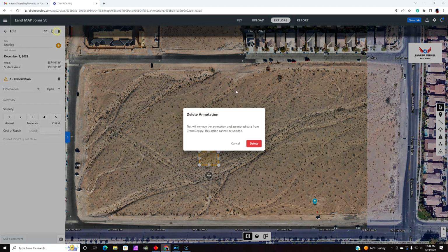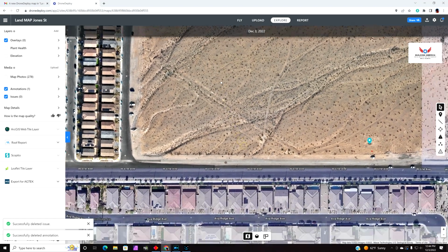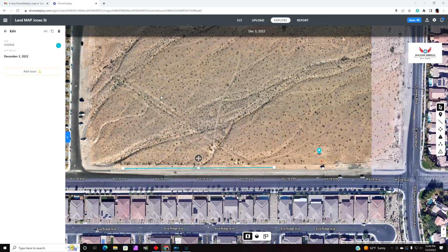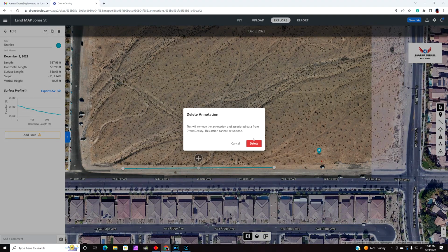We don't need to save that. So a lot of valuable stuff. Again, if we were to use our distance tool, it can actually give us a distance, and it's also going to give us a slope. You can see which way the land is sloping. And it's sloping at 1.74%, the slope of the land going across. So that's pretty neat. Again, no need to save any of this information.